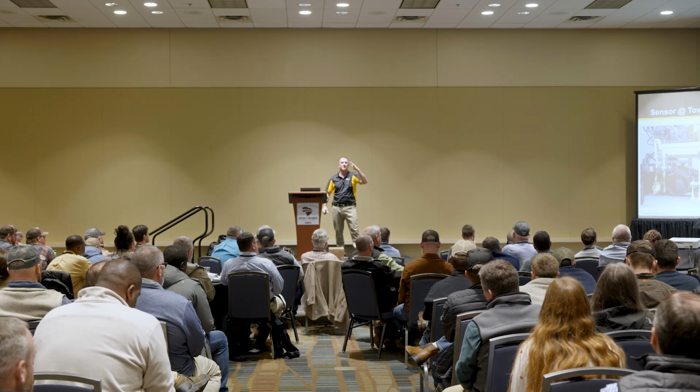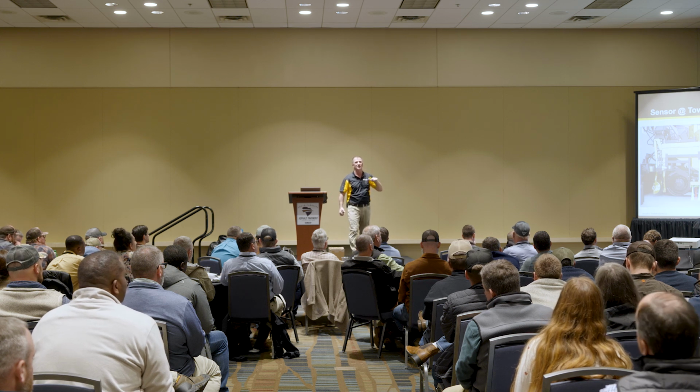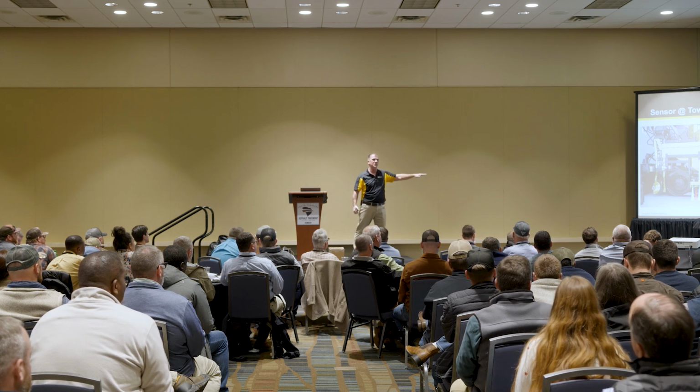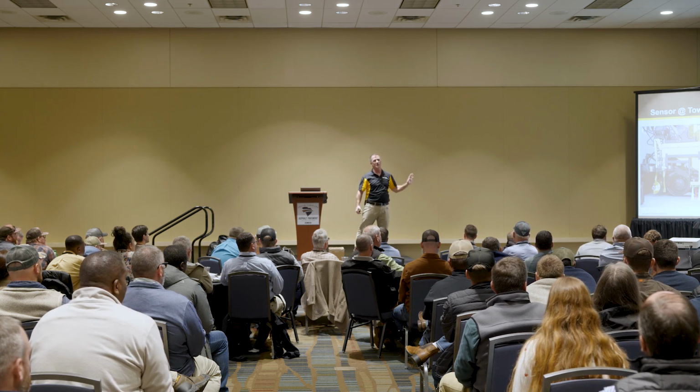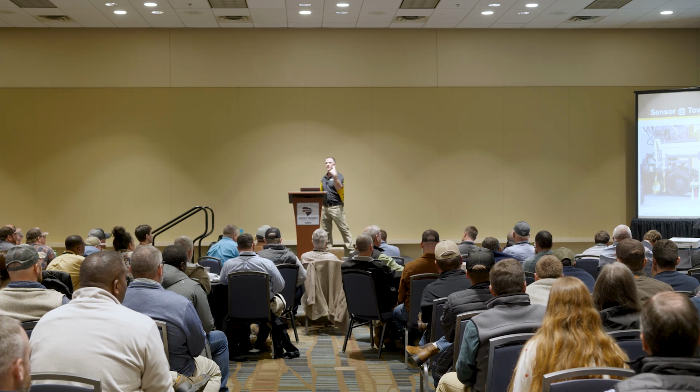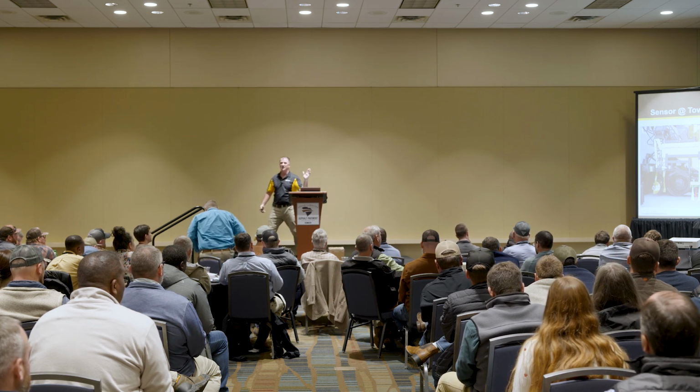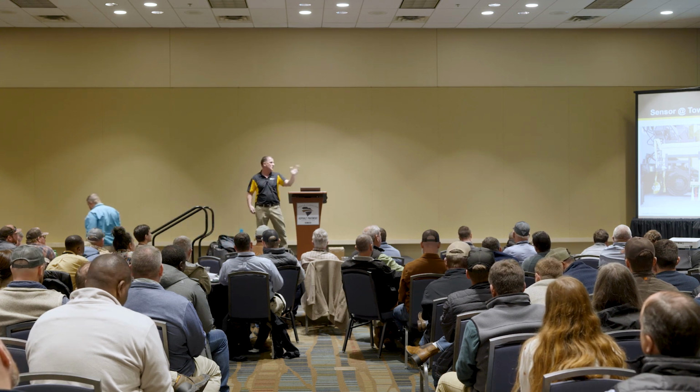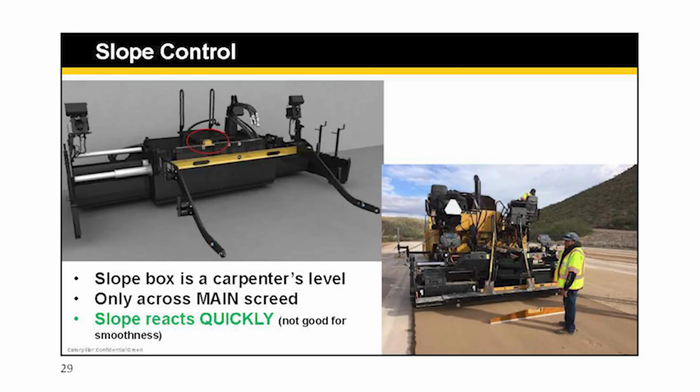So you don't have a big change in angle of attack. So what you get here is a lot smoother ride. It's still going to follow the grade, it's still going to maintain a thickness, but it's going to be a smoother change. So again, just depending where you put that single grade sensor makes a big difference.